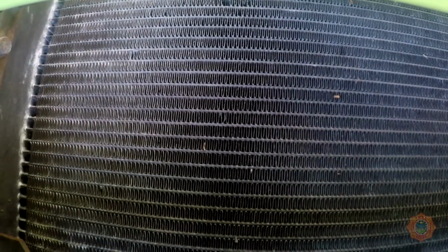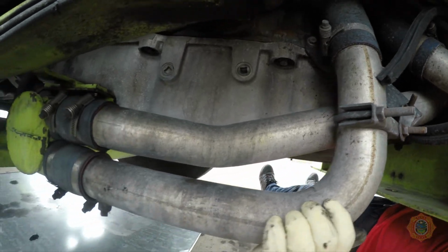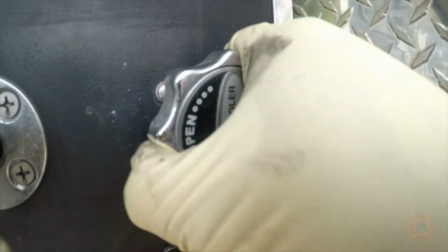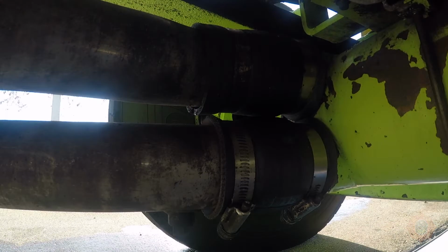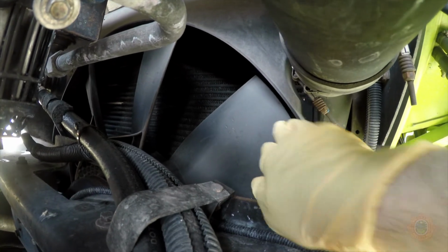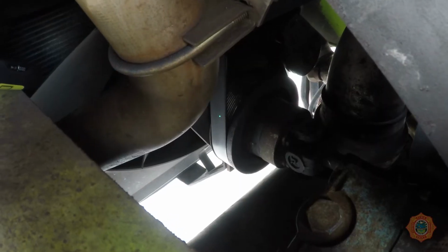Remove any debris, such as leaves or trash, resting against the radiator or air intake that will prevent airflow across the radiator fins. The lower radiator hose goes through the heat exchanger. Water from the pump flows through the heat exchanger and cools the radiator fluid. Inspect for leaks or physical damage. Inspect the cooling fan for any cracks or missing blades. Check the belt.